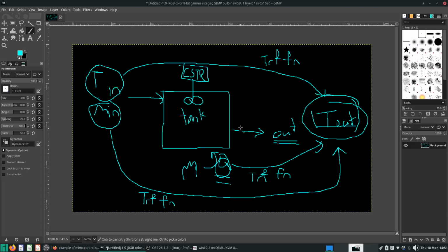Now the other method, of course, is that you have a multiple input, multiple output transfer function, also called MIMO. But in this case, we only care about the outlet temperature, so maybe we can consider this a multiple input because there's temperature of the inlet, mass flow rate of the inlet, and Q rate, the heating rate, and of course you have a single output, which is what you want, the outlet temperature. Of course, I made the very simplifying assumption that there was no heat loss. So this heat loss is controlled by some heat transfer coefficient, some ambient temperature, etc. And this can even be a fourth variable, T infinity, the ambient temperature. It's going to be the fourth variable that affects this T out.